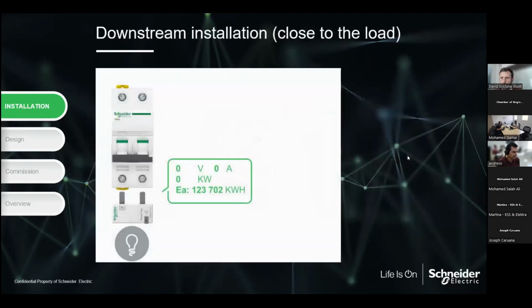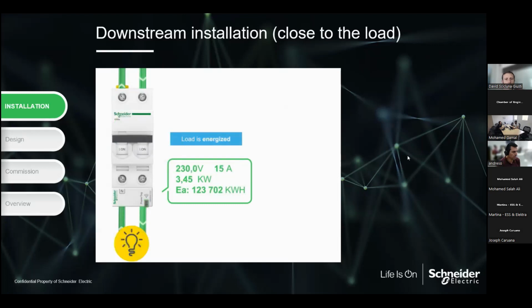Okay, and here is the difference between putting the power tag on the top of your breaker or on the bottom of your breaker, and it differs because of which side is closer to the load. If you put the power tag closer to the load, you can get the advantage of voltage loss detection, which is when the breaker is tripped. So you can get a small alarm saying that you have something wrong, like you see in this illustration video.